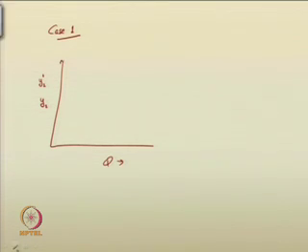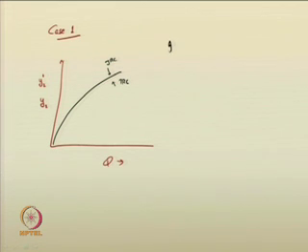In this case, if the tailwater rating curve TRC and the jump rating curve JRC are the same, what does this imply? It implies that y 2, the jump depth, and the tailwater depth y 2 dash are both the same every time.